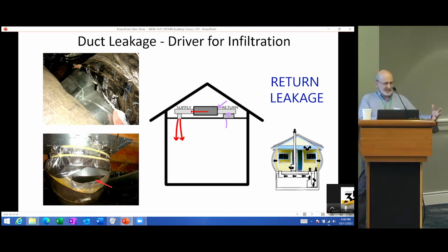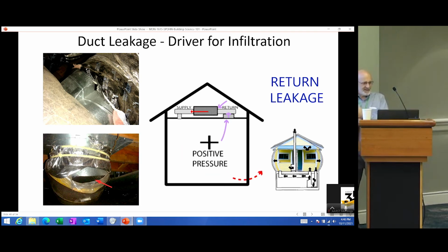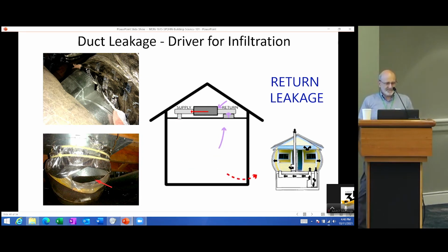If it's relatively comfortable inside, 50% humidity, you're now going to be driving that 50% humidity air out through the interstitial spaces, perhaps hitting a surface which is below the dew point for that air and causing internal condensation, and there's an opportunity for mold growth and just degradation of the material.